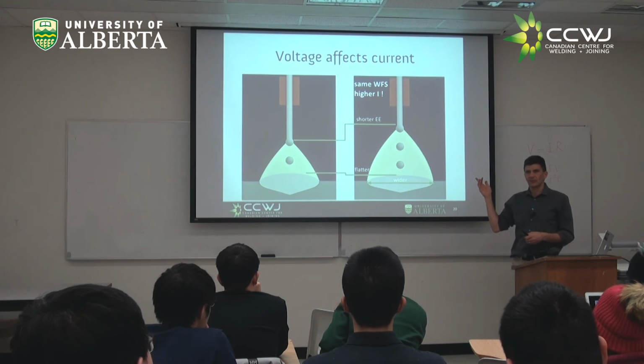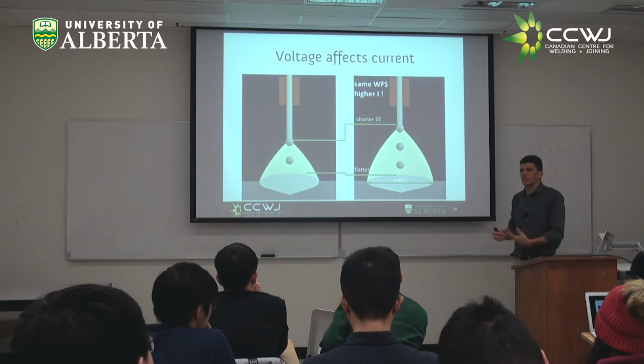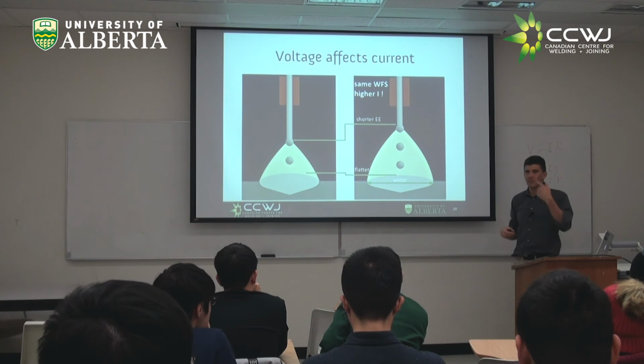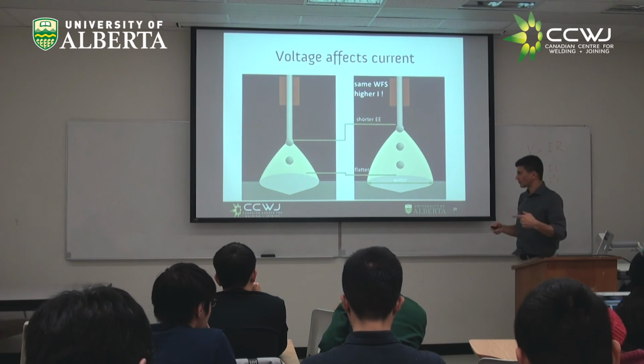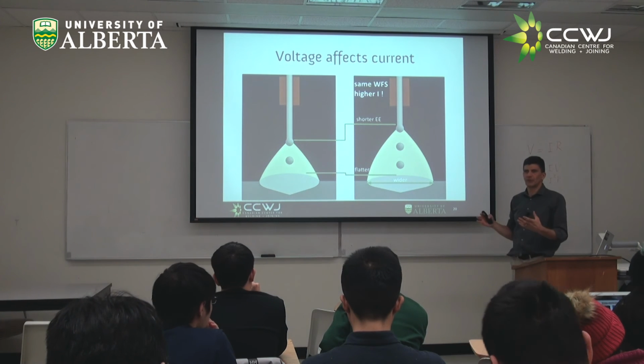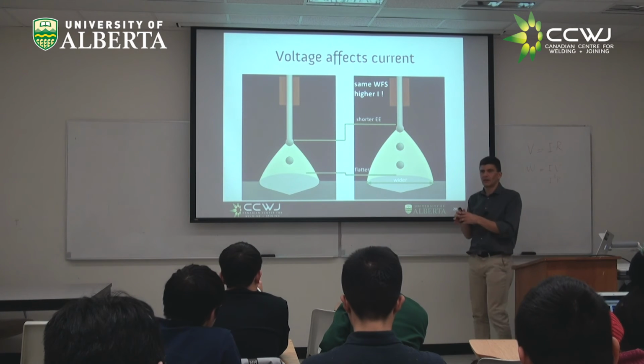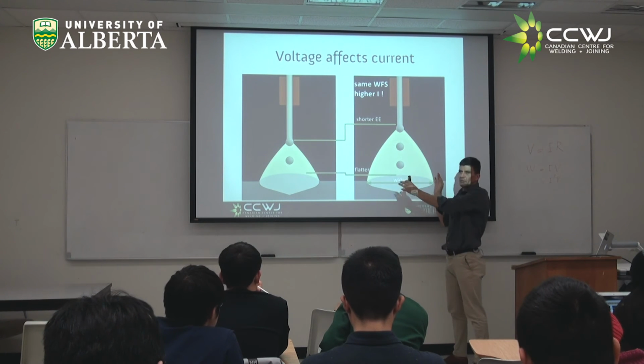And this is the reason. Because the machine all of a sudden realizes it needs to give it more juice to keep melting the same amount of wire. If the current went up, you're going to have some higher penetration probably. You're going to have also, because if you remember the arc, I said it's like parabolic, it's going to be a wider arc.